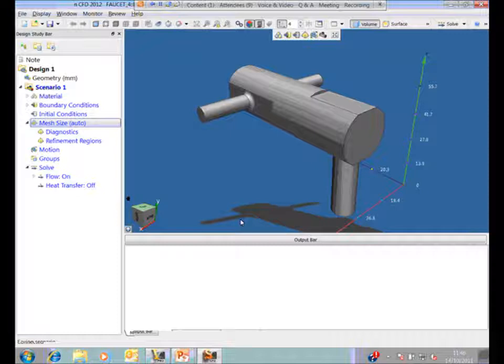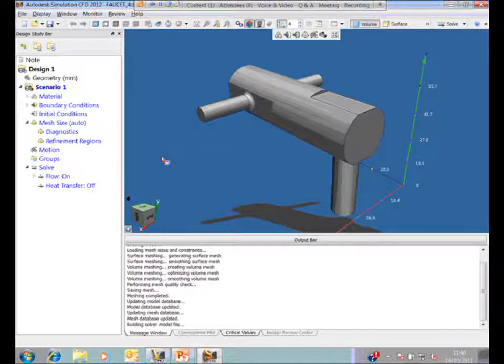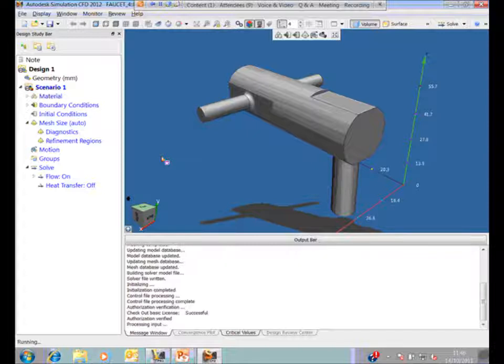I'm going to mesh this automatically, but you can, as per most systems, change the meshing of any of the parts should you wish. This will actually auto-mesh. You are able to edit the mesh with purely a slider. There's lots of uses of sliders in CFDesign, which makes life as an engineer much easier. But you have full control over the mesh of the parts in this assembly.